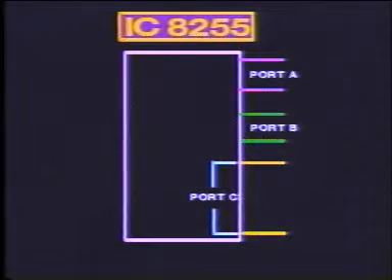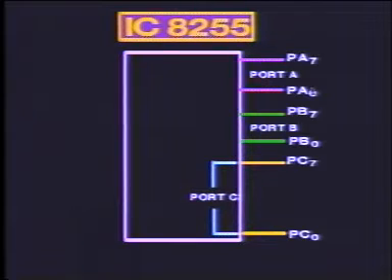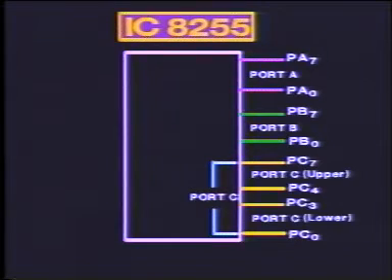The Intel 8255 is one such peripheral interface device. It can be used with the Intel 8085 CPU. So in this lesson, we are going to learn about the details of 8255. The device features three ports named A, B and C. Each one of them is an 8-bit port. However, port C can be divided into two 4-bit ports and used separately.